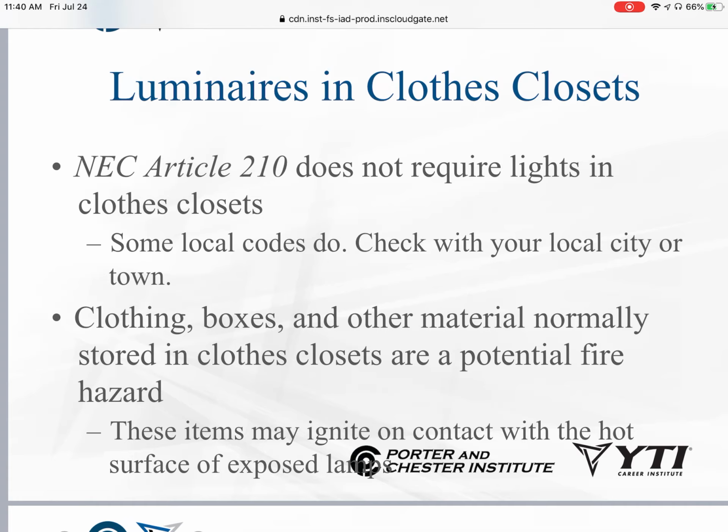Believe it or not, when it comes to closed closets, Article 210 does not require that closets have lights in them. However, there are local codes and local jurisdictions, and for instance in Massachusetts we have the Mass Amendments.